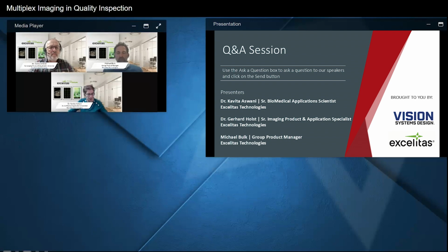What's the difference in using a broadband illumination and color camera compared to multi-band illumination and using a monochrome camera? I would say resolution. Because in general, if you take your actual smartphone cameras, then they have different color filters on each pixel. So most popular is the so-called Bayer pattern, which has 2 green, 1 red, and 1 blue filter, set of 2 by 2 pixels.